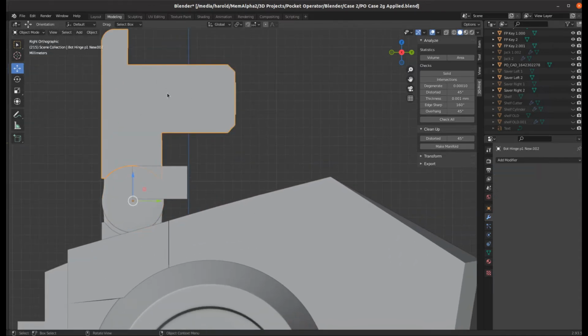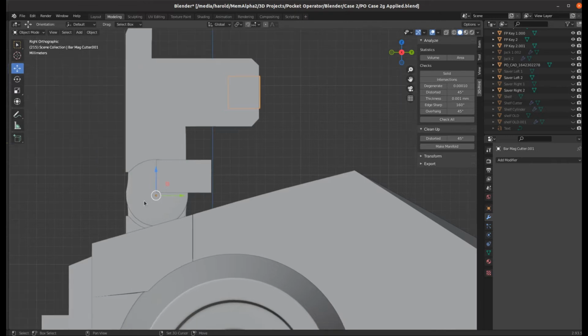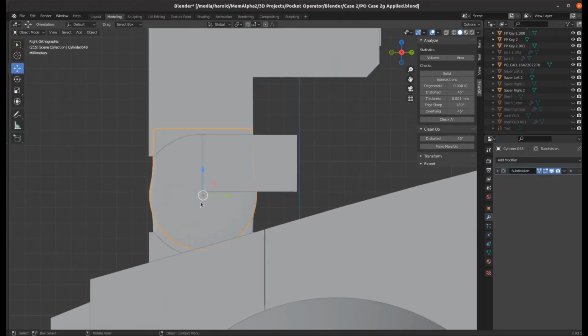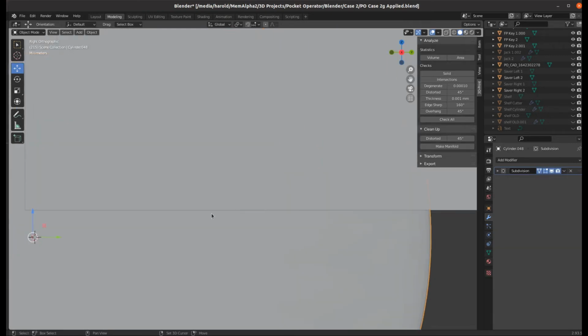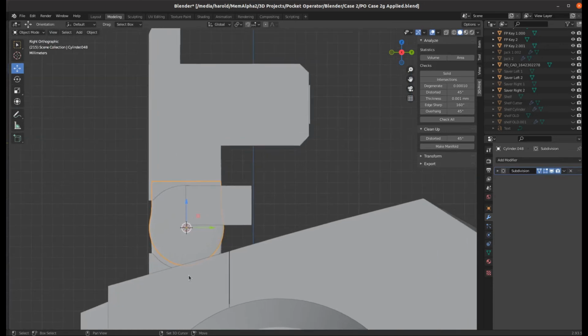This is the top part of the hinge. I moved the origin point down to the center of the hinge pin. Here's the magnet. I moved that down to the center of the hinge pin. And all you do is you select the object you want to move the 3D cursor to. You hit Shift, right select, and you can zoom in crazy amounts, right? We're looking at it in such tiny, tiny amounts, it doesn't really matter. But I like to get it as exacting as I can.